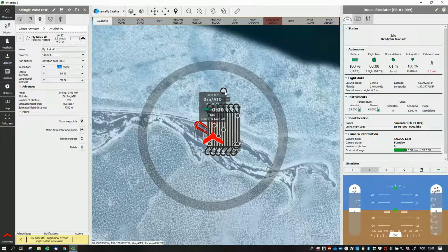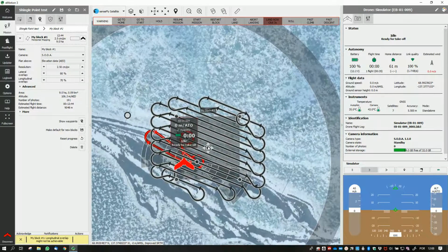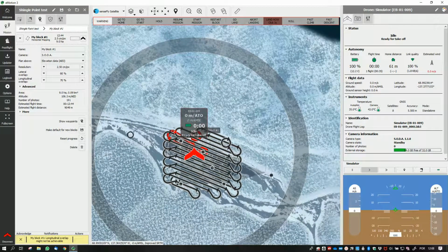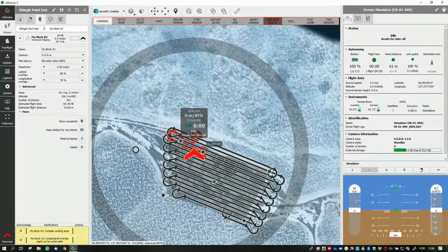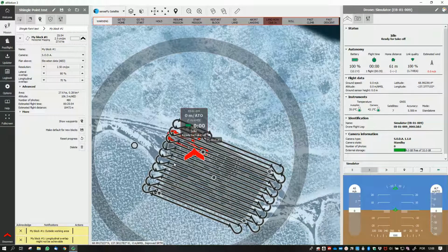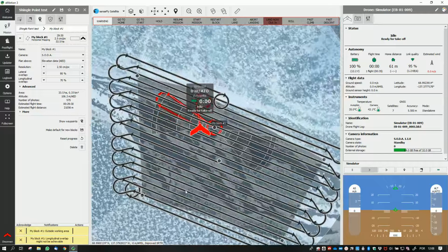So let's do a bit of a test here. Normally what we do is fly along the coast so that we avoid the time flying over the ocean. And we will move our flying area to pick this sector. Here, here, here, here. We can add another point here just to follow along the coast. Have a look at the flight time, and it's already 30 minutes. As I told you, I wouldn't like to do more than 30 minutes of flight time, and now it is 29 minutes.